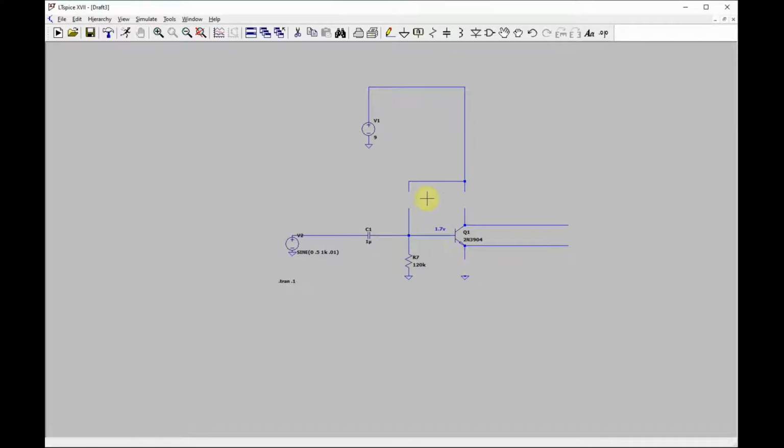When you usually build these circuits, this is your lowest resistor. It offers the least impedance to the formula. So if you step this up just one hair, and then fill these other ones in, when you parallel all three, you end up getting something around 100K in this case. That's where this is coming from.